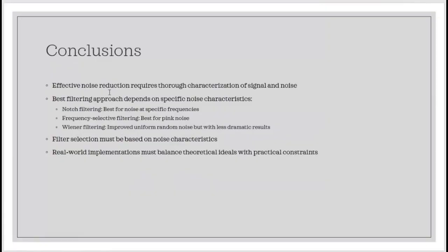Lastly, an important consideration throughout this project was the distinction between ideal and real filters. Ideal filters have perfect characteristics with infinitely sharp transitions, perfectly flat frequency responses in the passband, and infinite attenuation in stop bands. However, real-world implementations face limitations, including causality requirements, finite order constraints, and computational complexity trade-offs.